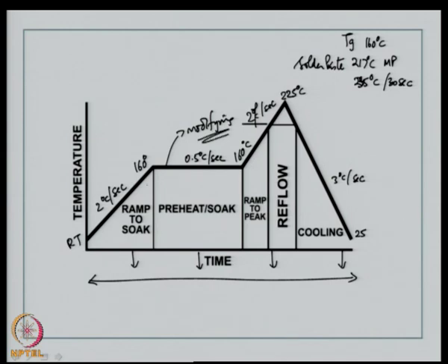So, this is also workable because you are trying to activate the entire system at 160 degrees centigrade, and then you are moving from 160 to 225 without a residence time, and then getting back to room temperature gradually. So, typically this also you should end up in about 225 seconds, which is less than 5 minutes and acceptable for the industry process.